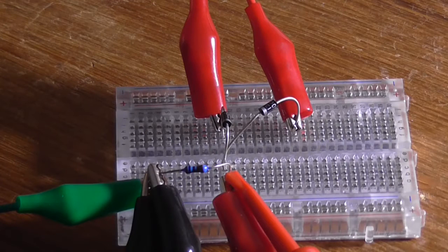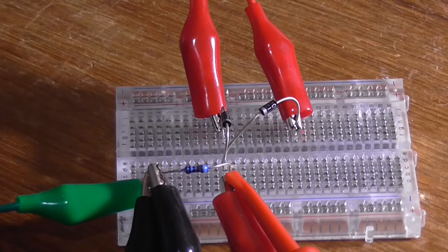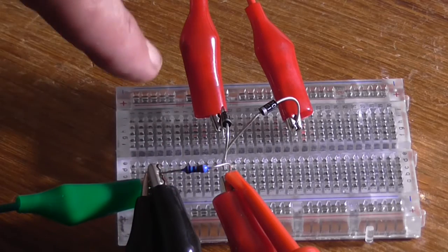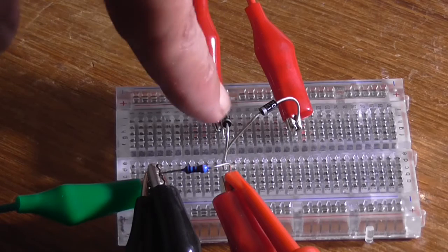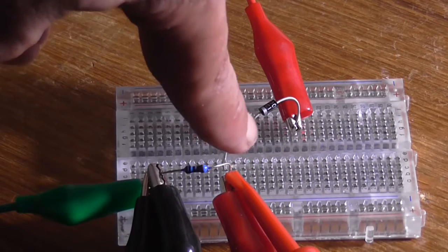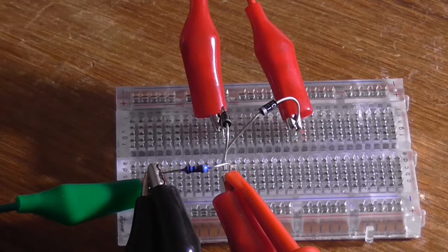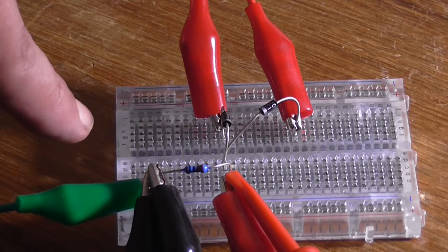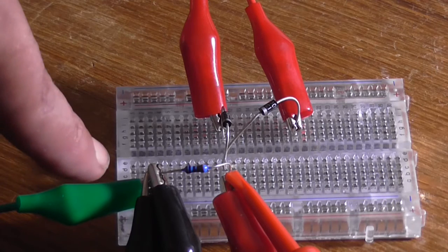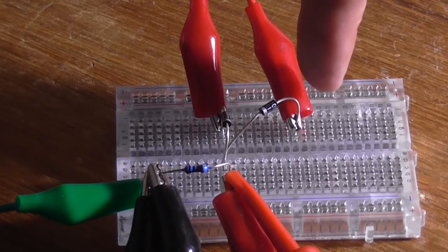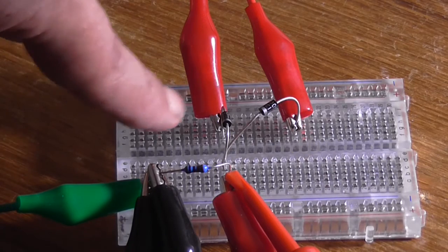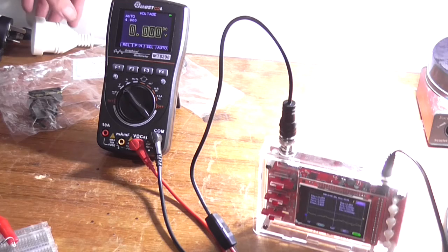And welcome to our second type of rectification circuit, the full wave rectifier. Now the setup's the same. I've still got the 10k load resistor here on the output. The two cathodes of each of these two diodes connect together to form the positive. It uses a center tap transformer where the center tap winding between the two 15 volt windings becomes our negative. One 15 volt winding goes to the anode of that diode, and the other 15 volt winding goes to the anode of that diode. Alright, and I'll plug it in there.